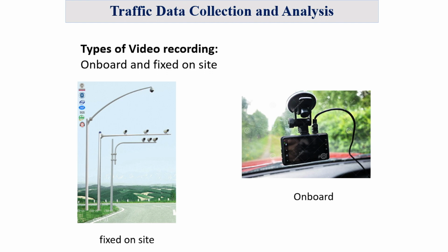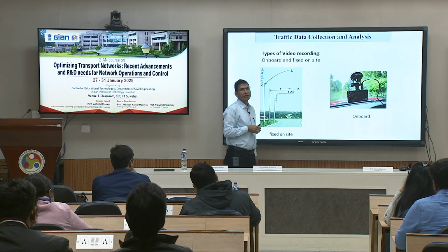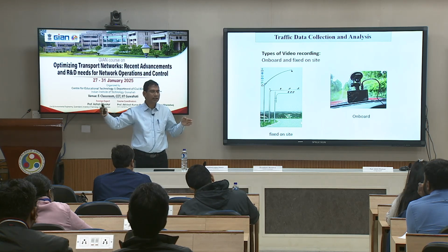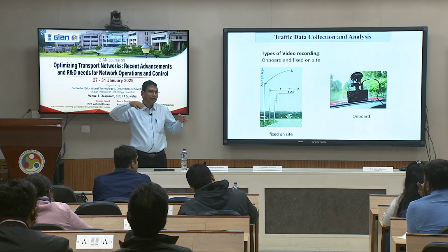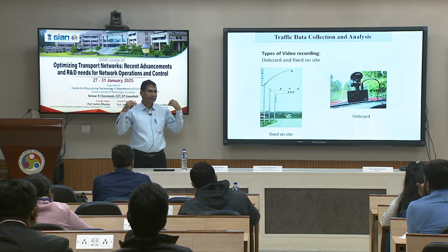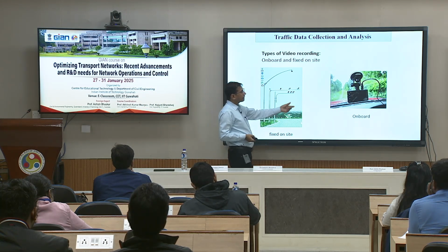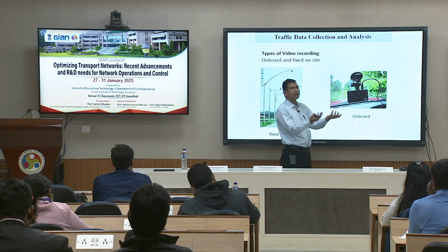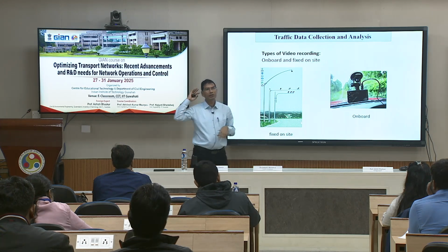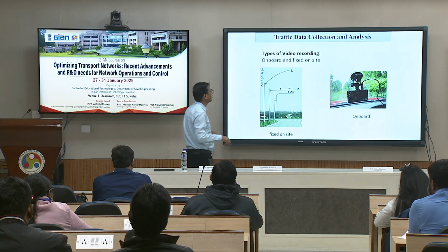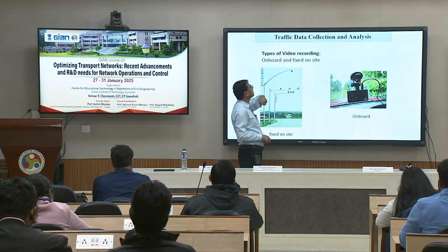In the other case, you place the camera on the dashboard of a road vehicle and then start driving in the traffic stream. In that case, you can cover as long a length of road as you drive, but here your pilot vehicle will be fixed. Whatever vehicles are in your surrounding, you will be able to get only those vehicles' behavior. So in one case the site is fixed, in the other case one of the vehicles is fixed and you will be able to study the surroundings. You can travel 40 kilometer, 100 kilometer and whatever is surrounding keeps changing, you will get the surroundings information. Okay. So on board and fixed at the site.